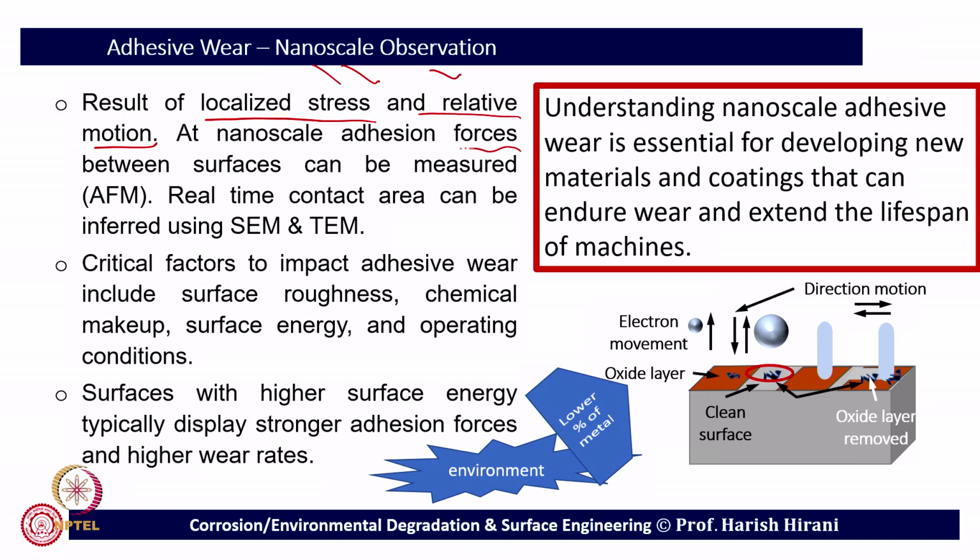The question comes, can we really measure the adhesive force between the surfaces? Yes, it can be measured when we use atomic force microscopy. Similarly, we can infer what will be the real area of contact, the actual area of contact. The Archard equation gives us some sort of qualitative measure, but if you want real quantification, then we need to use some sort of microscopy or maybe profilometry, and we need to infer from that using image analysis, using an image which has been taken from a very good source.